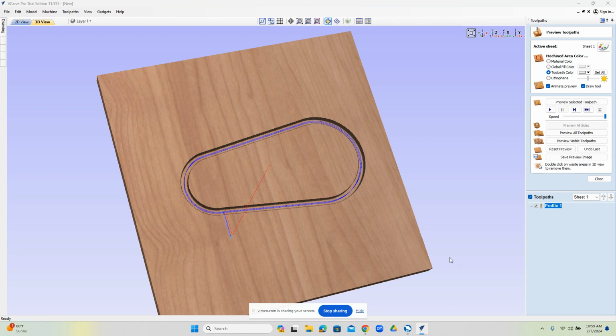You had a radius lead, but similar type concept. So now when we play this through, we can see a straight cut on the plunge, comes in, goes around the part, and then comes back out. And again, you're saying you're getting some kind of burn here, but we don't see a burn anywhere else on the part, only where your lead in position was.